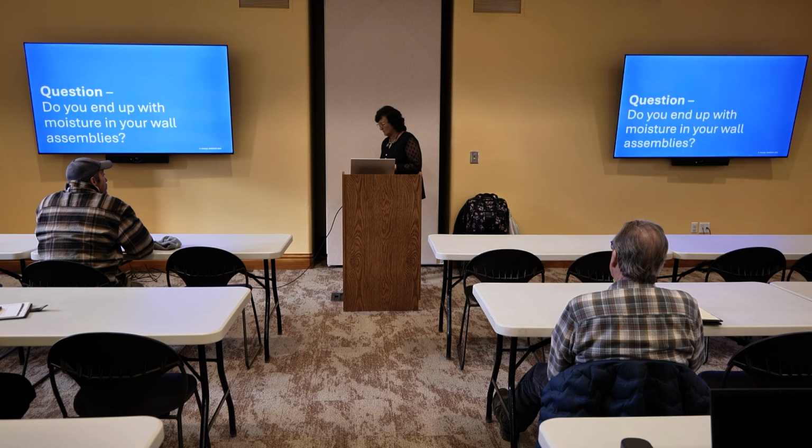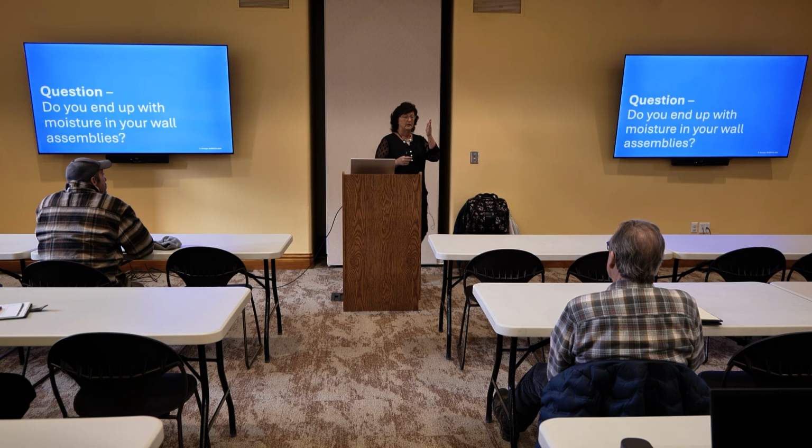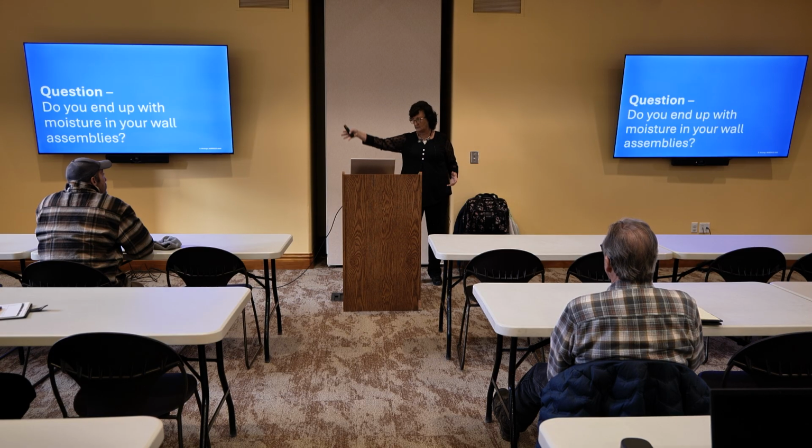You might have to, depending on what you're doing, what's allowed. But it's really up to the designer to look at the whole assembly plus the climate and the temperature and the relative humidity and say, here's where it's going to condense. When the cold air outside meets the hot air in the house, where in that assembly is it going to condense? Most likely on the sheathing.